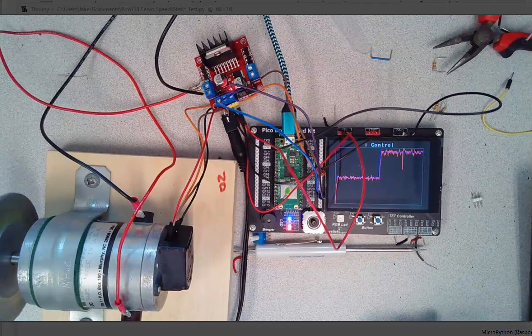So here's my setup. I've got the Pi Pico, my H bridge, the encoder, power and ground, go to 5 volts of ground. The two PWM outputs go to my H bridge. 15 volts, meaning 13.4 volts out, comes in as power. This goes to the motor. And after it collects all the data, it will plot the voltage versus speed.